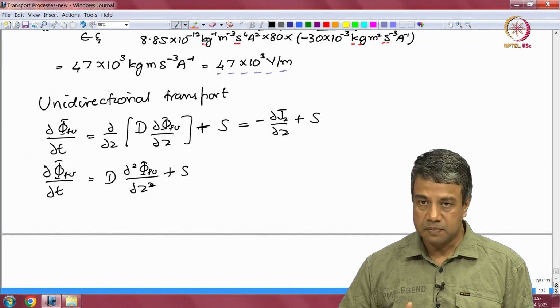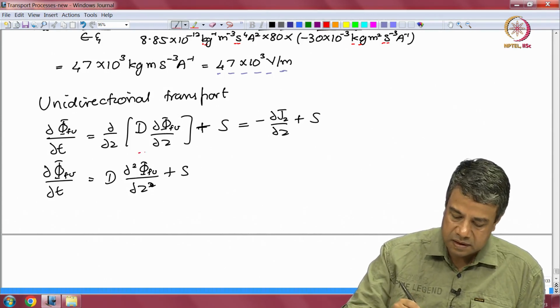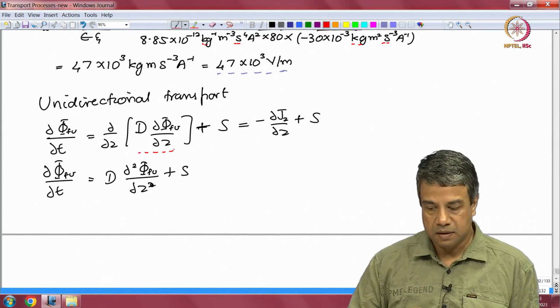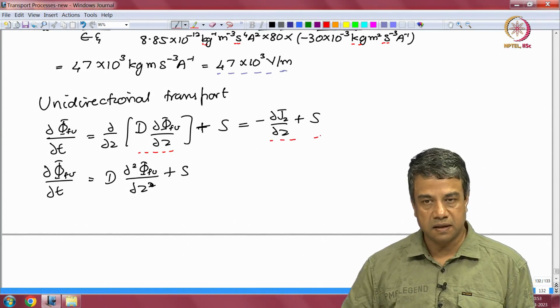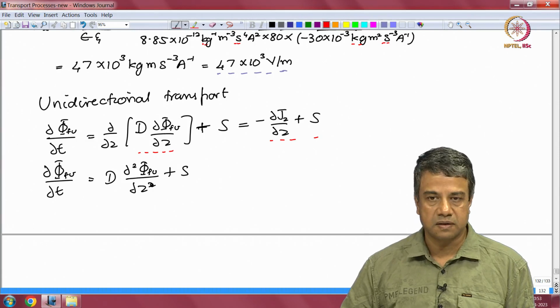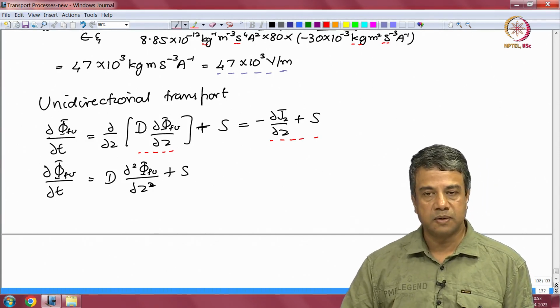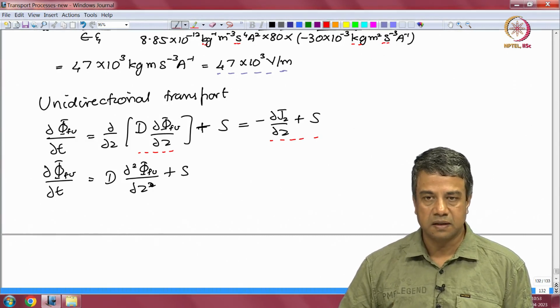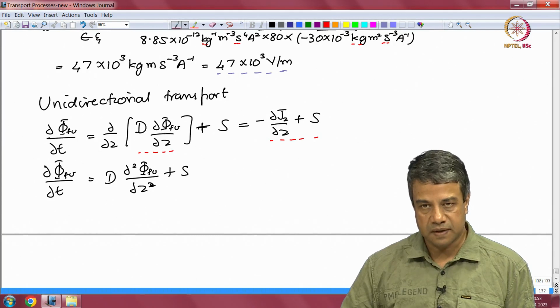Flow down an inclined plane of a power law fluid, the constitutive relation is different from this one, but still this equation applies. The flux is still a linear function if the source is a constant. The relation between the flux and the velocity, or the stress and the velocity, is nonlinear, and we saw how to solve that problem.